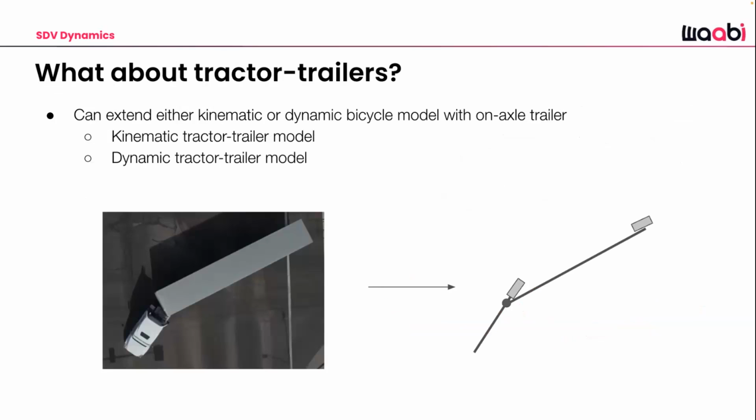Yeah, and I talked about earlier that we can extend these types of kinematic and dynamic models to multi-body vehicles, such as a tractor trailer setup for a self-driving truck. There's a lot of work out there that covers this in more detail, but I just wanted to briefly talk about how vehicle dynamics are very key to simulate to update the state of your self-driving vehicle. And the fidelity you do it at is pretty important, especially for the self-driving vehicle. You might choose a bit higher or lower level of fidelity for the other actors in your scene.